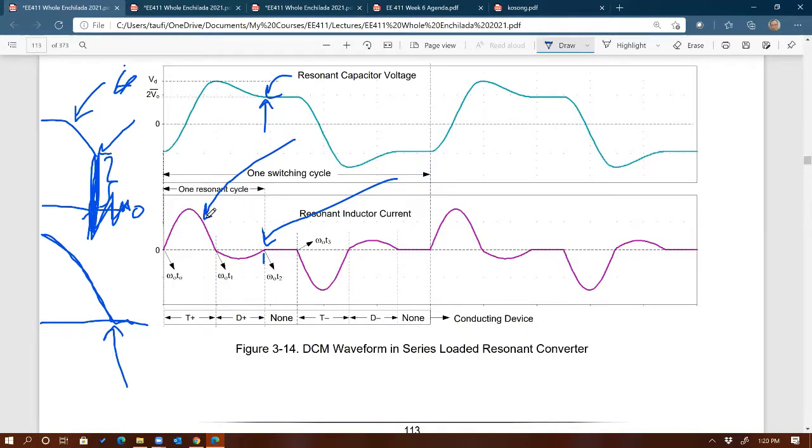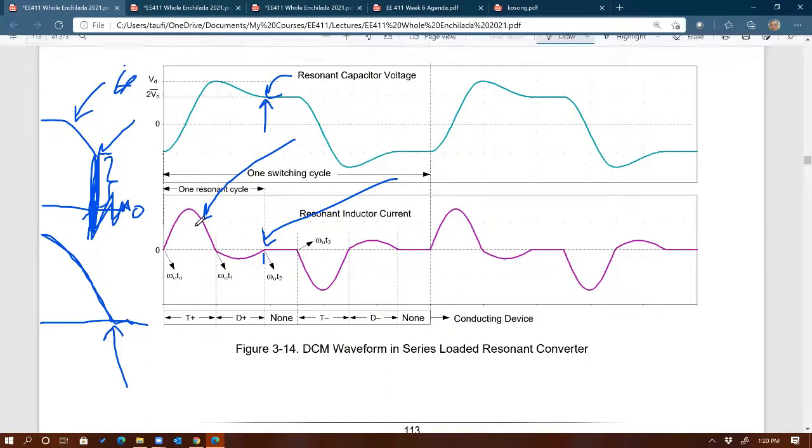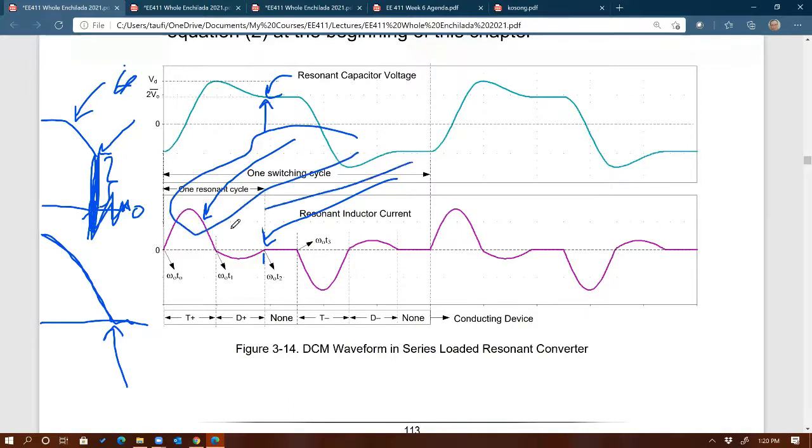And the same thing here, MOSFETs and IGBTs don't go that high in terms of voltage rating, also current rating. IGBTs probably can go up to 2,500 volts, but thyristors can go up to tens of kilovolts rating. So it is useful to be able to use thyristors for the switch and PN junction for the diode when it comes to high voltage, high power application.